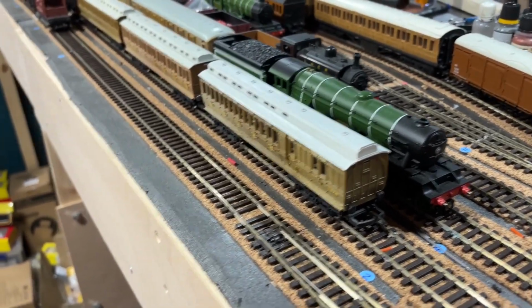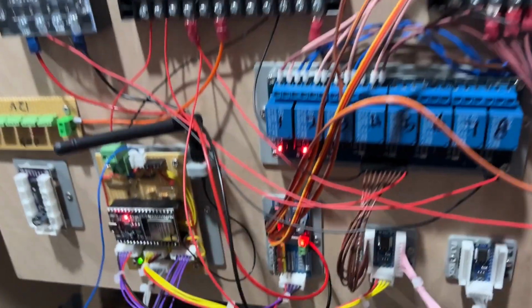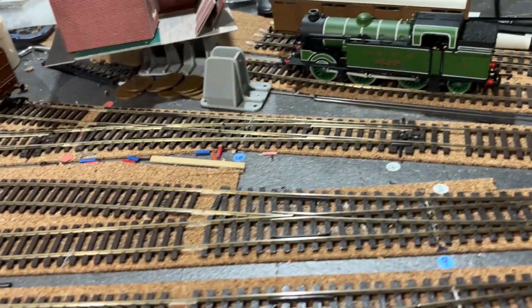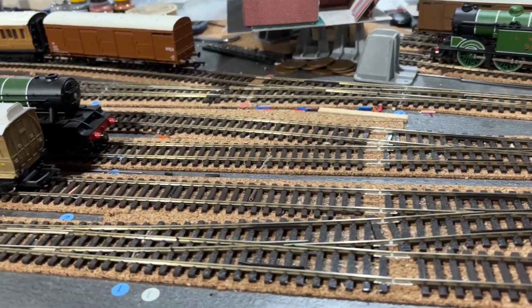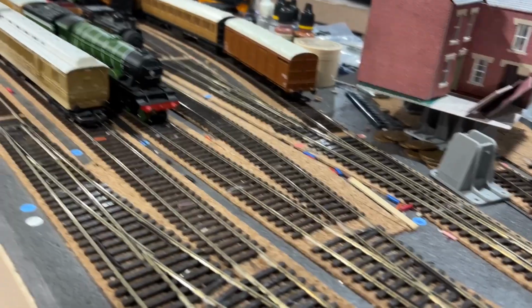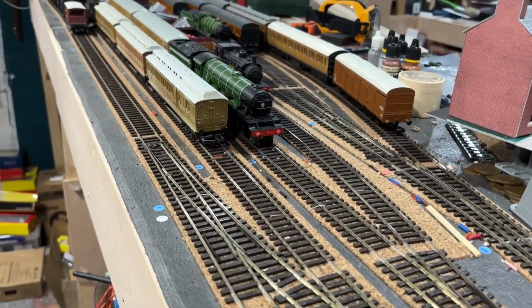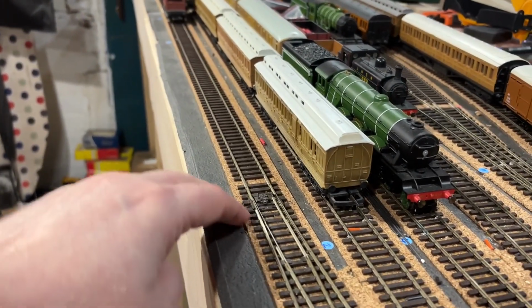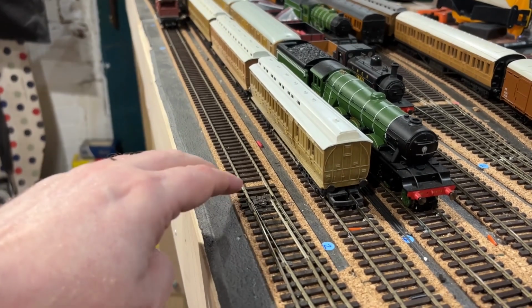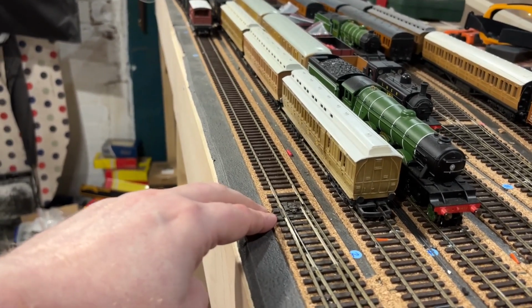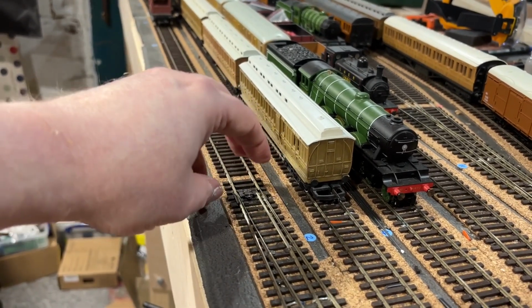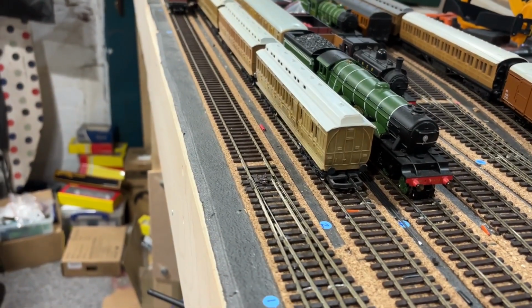So what I've got is the ESP32, and down here we have the one controlling these points on this board. This is board G, so it controls this one, over here, these, and then the ones in the back eventually. I will set up two imaginary switches, two virtual switches in the software that say where the point blades are. So look at this one here, point number 1. There is a virtual switch on this side, which will say this point is in the thrown position. There is a virtual switch on this side, which will say this point is in the closed position. And when the blades are moving, neither of them will say anything.